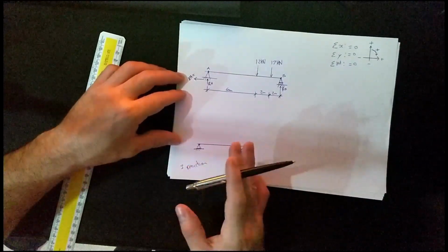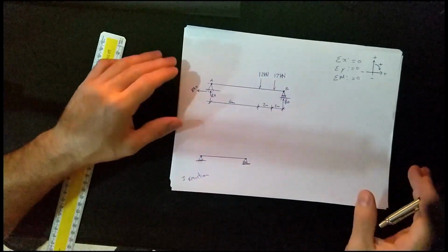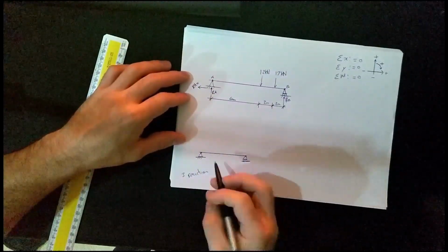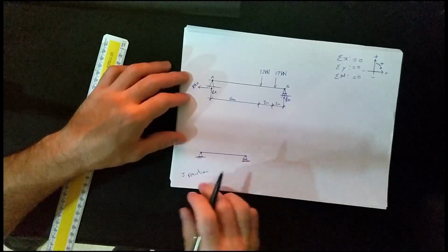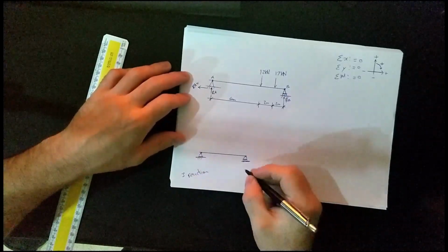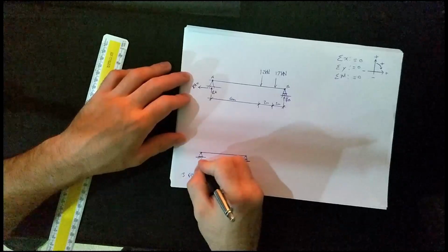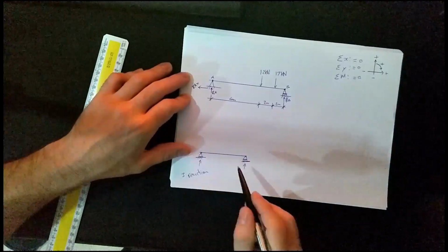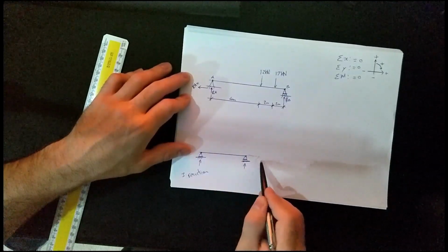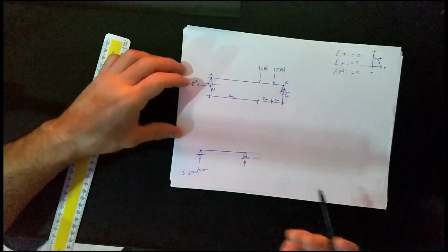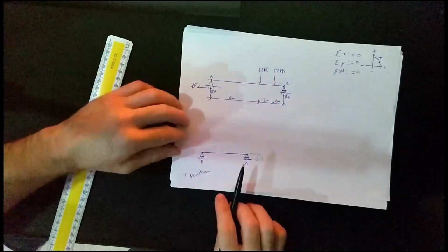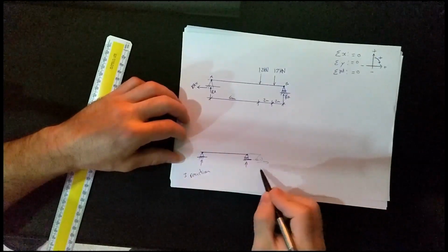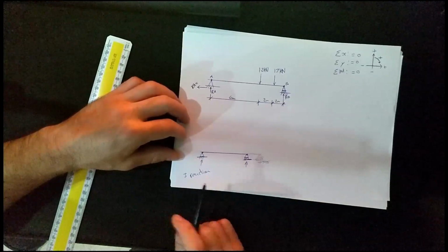Static, i.e. it's not moving, which is good. That's what we want. This is structural engineering. Things don't move. So the three reactions, you can work out if it's two supports, it's going to have a vertical support, and due to this rolling support, that means it's allowed to move if it wants to. It can move by this much or whatever, which means there's no horizontal restraint. There's nothing holding it there, which means there's no horizontal reaction force.